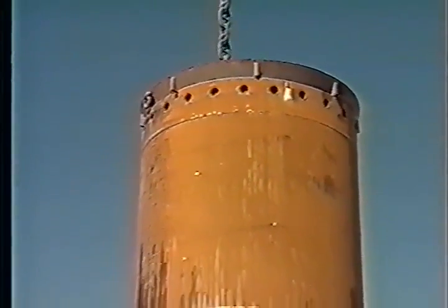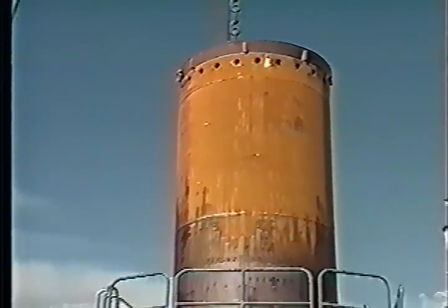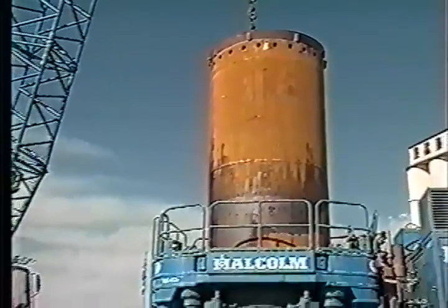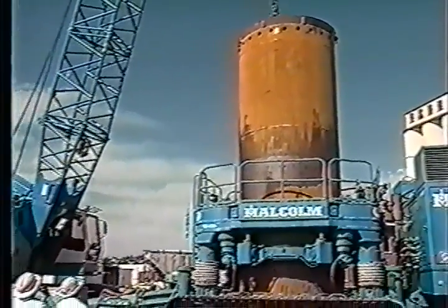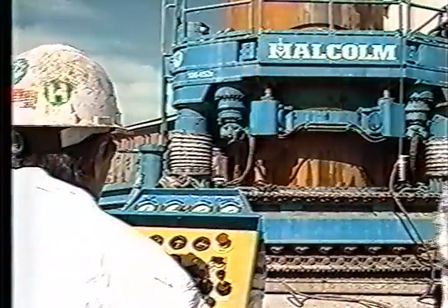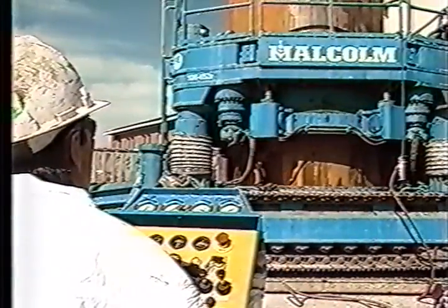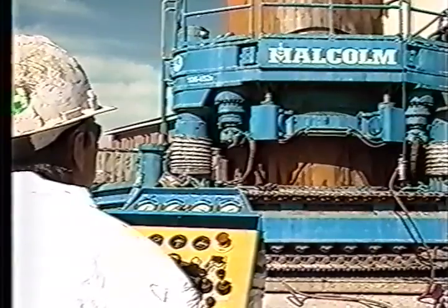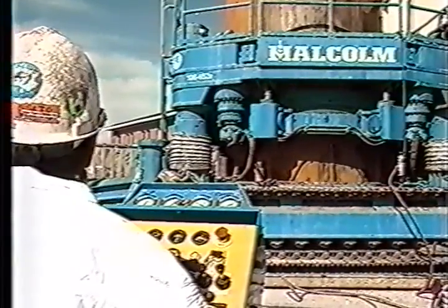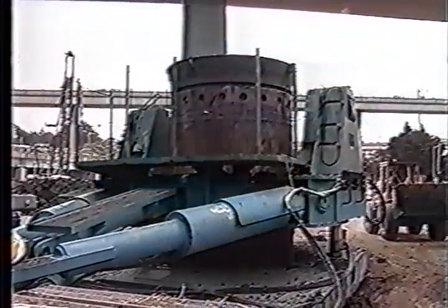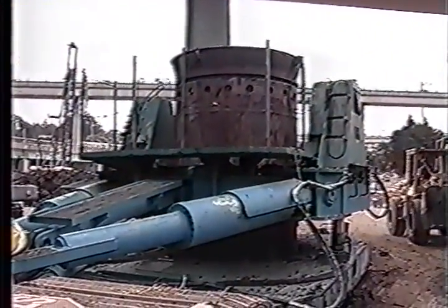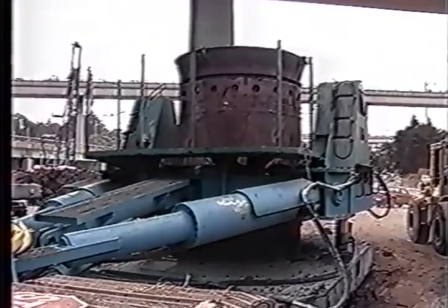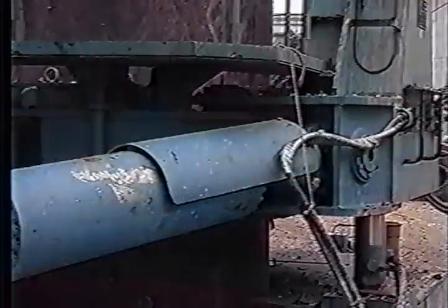Today in Europe, drilled shafts are predominantly constructed in a full-depth, cased way using oscillators and rotators. In North America, slurry-supported boreholes are more common due to the physical limitation of the equipment presently being manufactured in the United States. The oscillator rotator casing method utilizes a circular collar to clamp onto the drill casing.